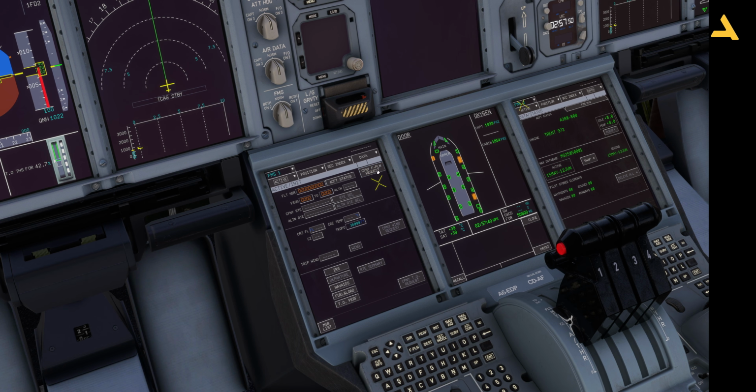Now you have to get the company flight plan, so just press this button and you will have the company flight plan. Then you can just insert it. Now you can see this message, company flight plan received, waiting for insertion. You can click it again and then you can insert. And now you can see the flight number is there, and the destination and the departure, it's there. Alternate is shown. And you have the cruising altitude, which is 39,000 feet for this flight, and cost index is really high, so plane will go at a very high speed, and that's it.